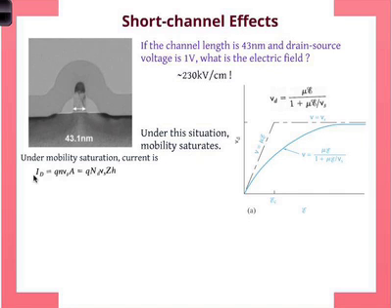So the drain current can be related to velocity very simply as the electronic charge multiplied by the electron density, multiplied by the velocity of the electron, multiplied by the area. Electron density times the area gives you the total number of electrons in that channel per unit length. Times q gives you the total charge, times the velocity gives you the rate of transfer of charge between the source and the drain. Remember, the electrons are moving from the source to the drain.